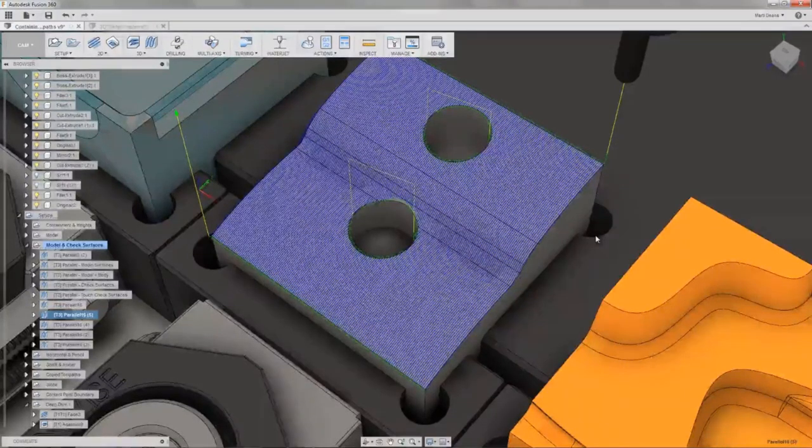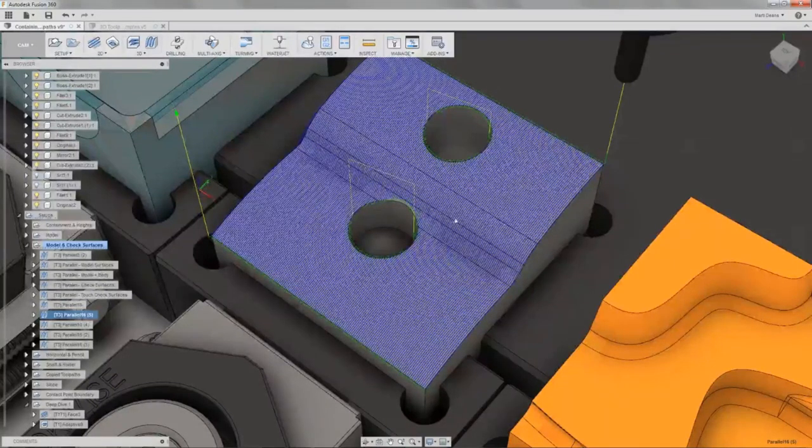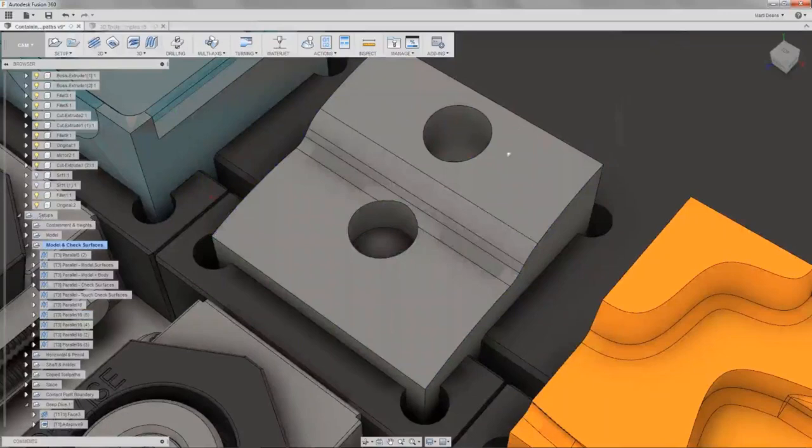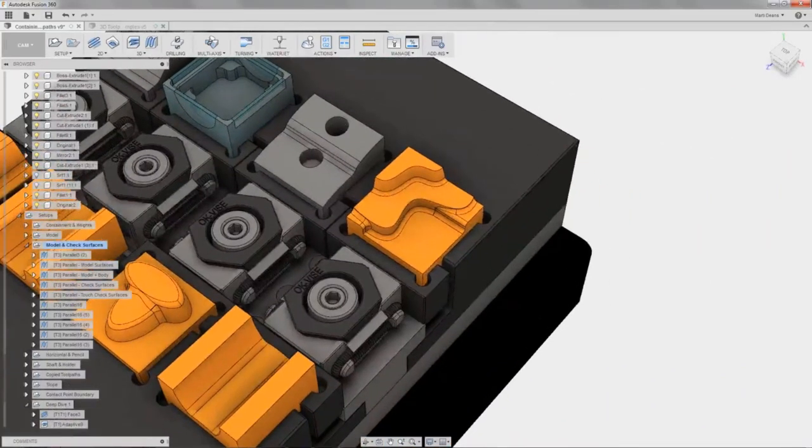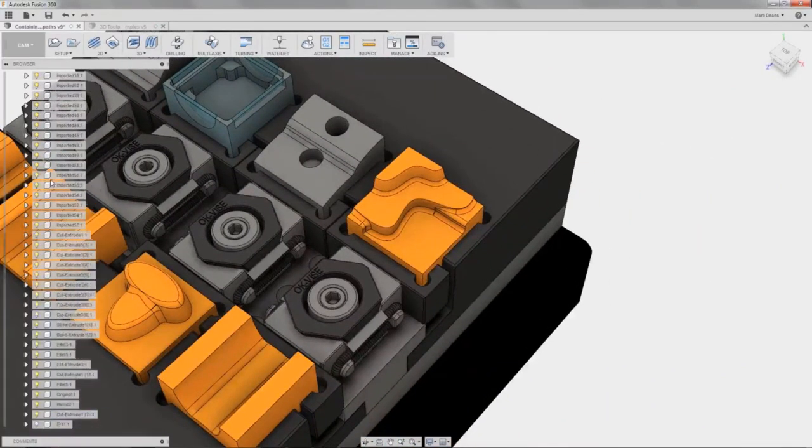And one side note on machining boundaries, you can also use a sketch. So like if this part I wanted to bound it to a square around the circle for some reason, I could also just use a sketch contour and select that. I don't have a good example of that ready, but it can be any edge or any contour. Okay,